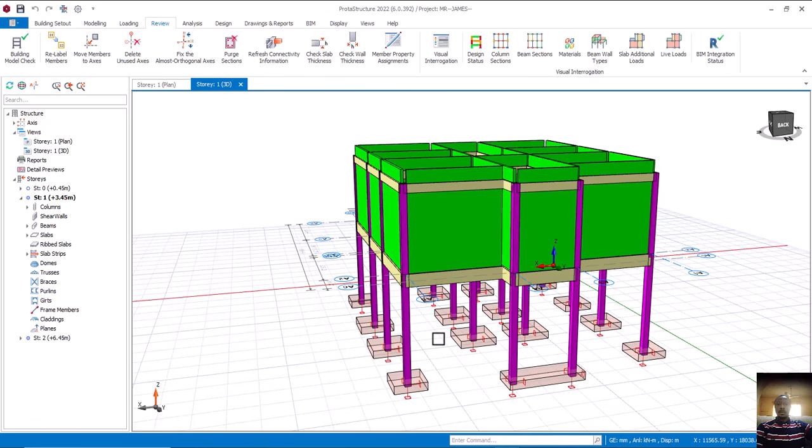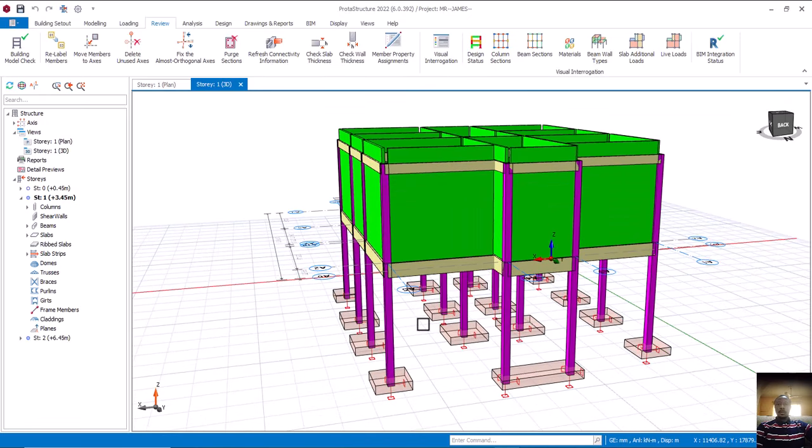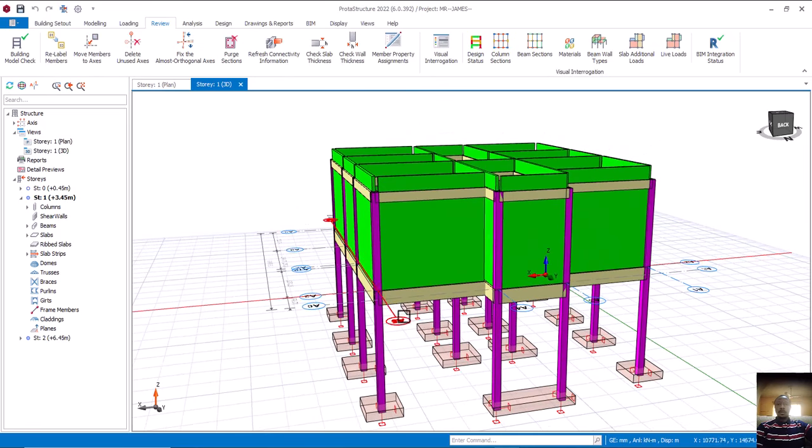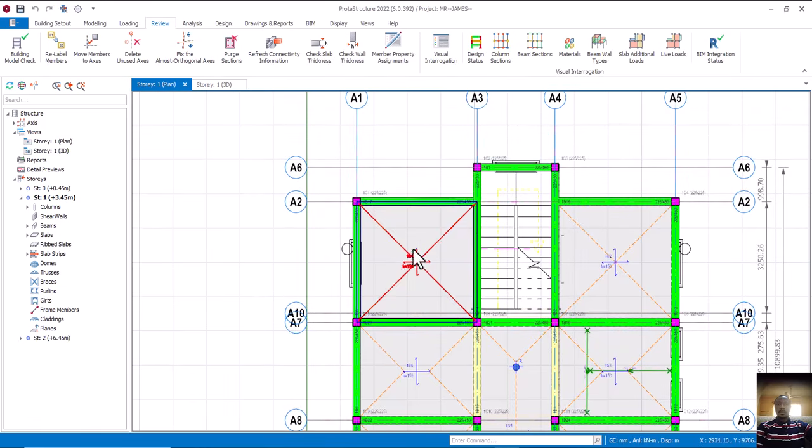Now number two, why we hinge is to reduce bending moment. When we introduce a hinge, the moment at that hinged end becomes 0. This is the point which I believe we all remember. During our manual design, beam end condition, for example, at this point, if you look onto the plan view, you can see this is the end condition. If you look at this beam now, this is the end condition.